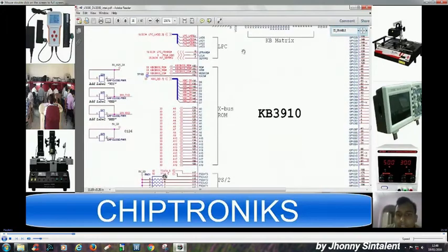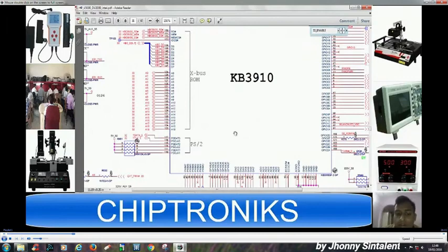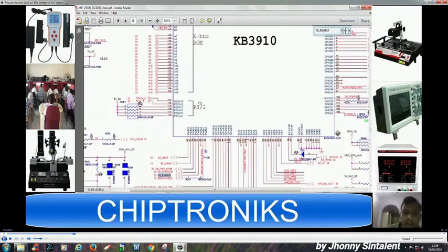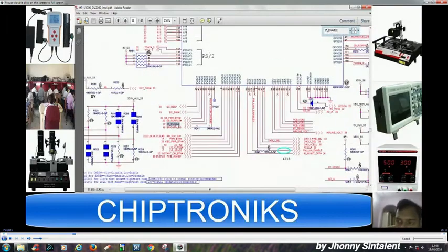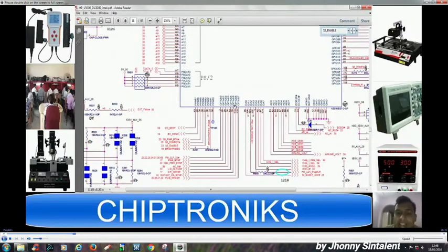So the EC has got the inputs. EC is reading with the EC BIOS. Now it will generate S5_ENABLE. Now there are two conditions. Suppose your notebook motherboard is connected with a battery. In that case, after you press the power button, this signal would come. And if your notebook motherboard is connected with a charger, then without pressing the power button, this S5 enable would come.